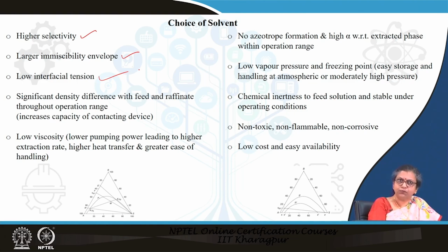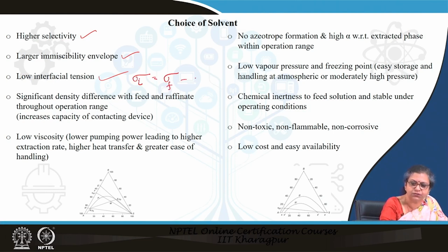I would also like to mention, normally data on interfacial tension is not available. So, often what we do is denote the interfacial tension as the difference between the surface tension of the feed solution and the solvent.